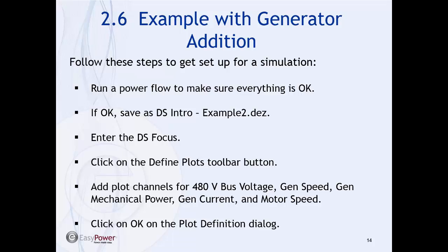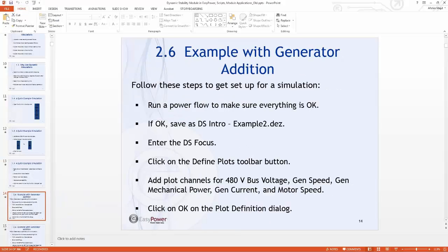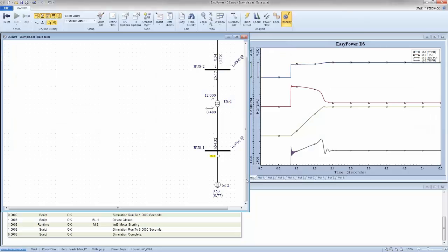I just don't know where I should use it. This is the type of application that you should be using it for. If you have a governor model, if you have an exciter model, you can't model it in any other module. The only way that you can model it properly is dynamic stability. So let me just go back, because it might not be completely covered.